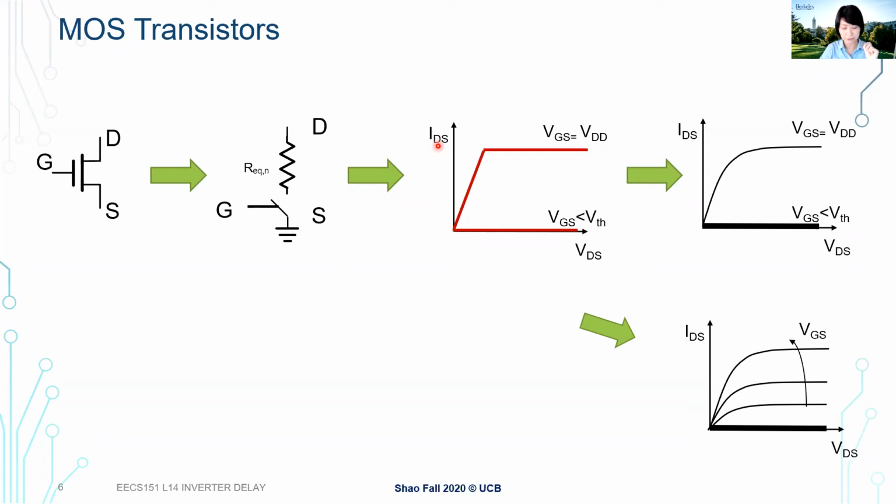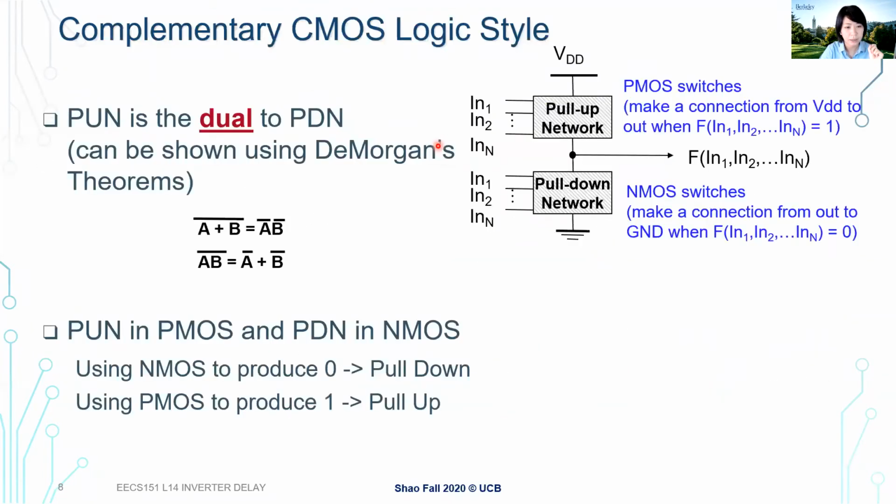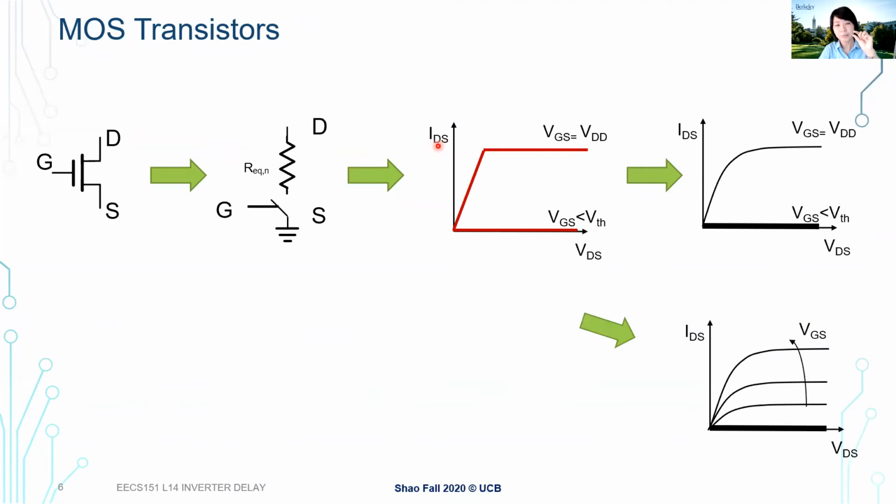So in the CMOS transistor, if we had a picture, we don't have one here, this is what they call the pinch off region. It's basically the channel doesn't exist, or barely exists. So the current can flow through, but the region close to the drain barely exists. You can think of it as having a fixed channel width at that point. This is the minimum channel that exists to keep the flow going, but that is not proportional to the drain to source voltage anymore for this region.